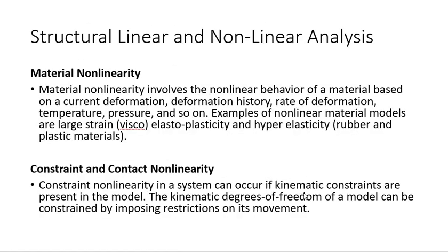Next is material non-linearity. So material non-linearity involves the non-linear behavior of the material based on its current deformation, the deformation history, rate of deformation, temperature, pressure, and so on. Examples of nonlinear material models are large strain, viscoelasticity, plasticity, and hyperelasticity, rubber and plastic materials.